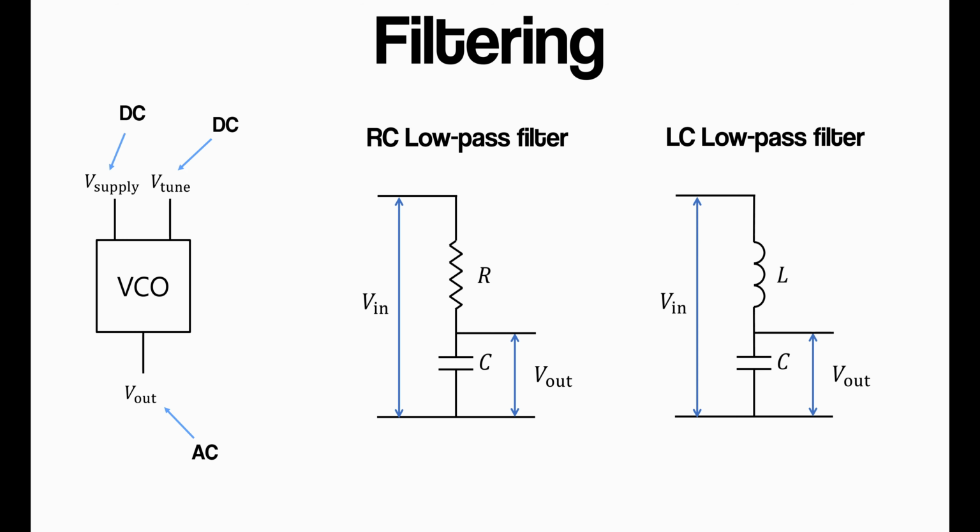So once we've found the resonance condition, we can pass our tuning voltage through a low pass filter, and that will basically remove any high frequency components to the tuning voltage. So say for example, we do have some noise on top of our signal. We know that the noise is going to have a certain frequency, and if we have a very aggressive low pass filter, i.e. we remove all signals that happen to have a frequency above, say, 0.1 hertz, then that will reduce or remove a lot of the noise in our tuning voltage. So this is a way to improve the noise on the voltage further.